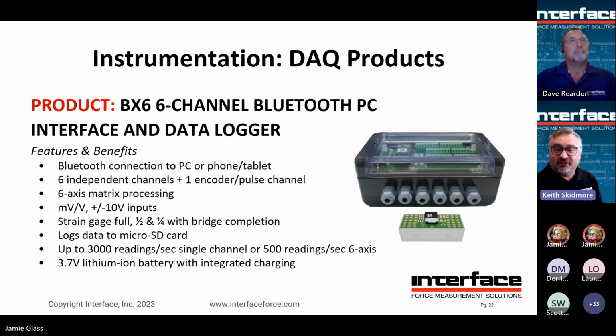This is a BX6, which is an interesting device. It's a Bluetooth and SD data logger. So it's a wireless connection to a PC, again compatible with our DAQ software. It can do the 6-axis calculations internally and process the data and then store the actual resolved data to the SD card or transmit it over Bluetooth to the PC. Both of those can be done simultaneously.